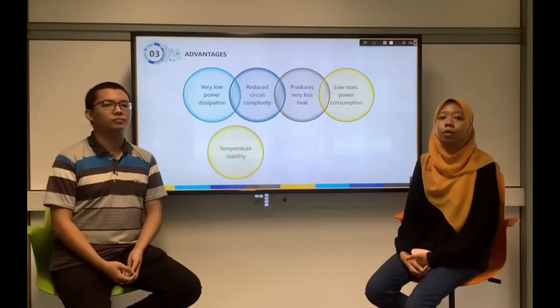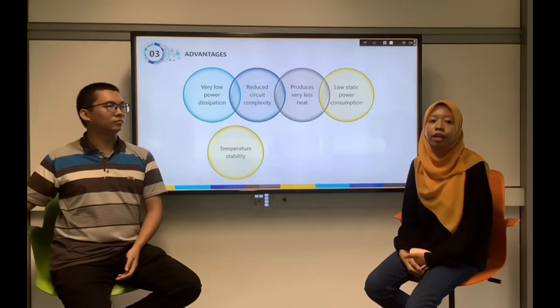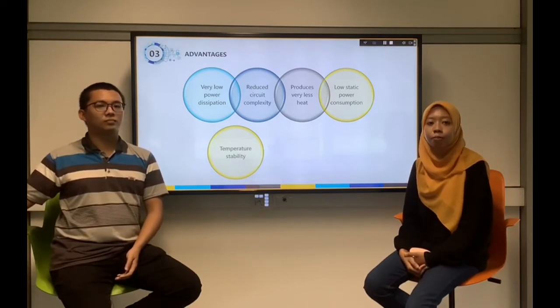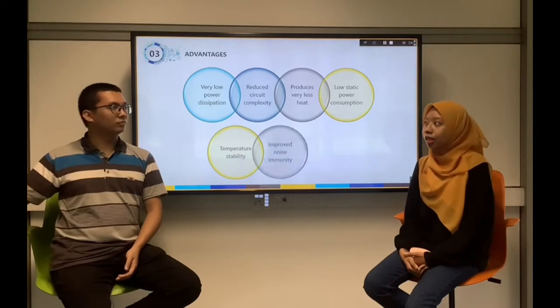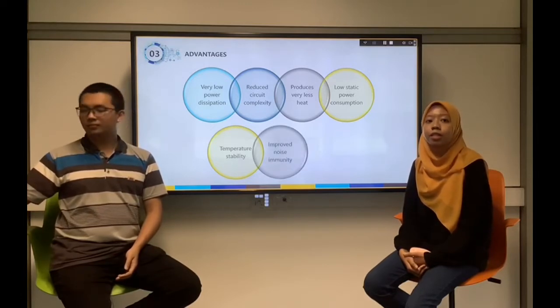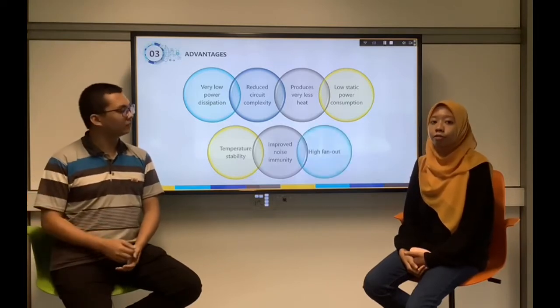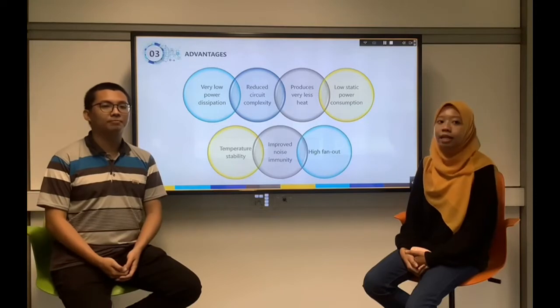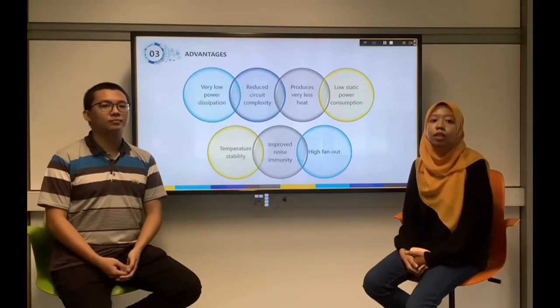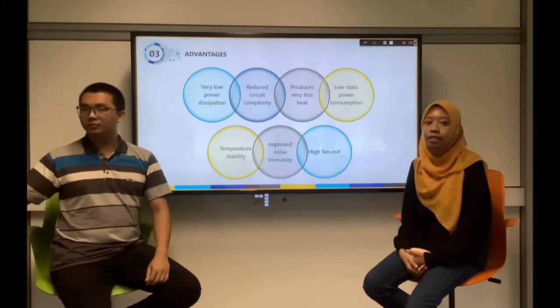CMOS is stable in a wider temperature range, which is around negative 55 degrees to 125 degrees Celsius, compared to the other logic circuits. CMOS has the highest noise immunity, which means it can still function well in the presence of noise interference. Lastly, CMOS has a high fan-out feature that measures the load ability of a logic gate. Fan-out specifies the input gates driven by the output of the other gate.